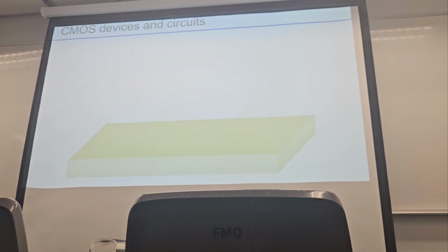Straightforward, from the bare silicon, and then we have the pad oxide deposition. For the most part, we always have the pad oxide at the beginning because we need to use oxidation, not CVD, to get a high quality silicon dioxide thin film to guarantee the threshold voltage. And then we always need silicon nitride as a hard mask.